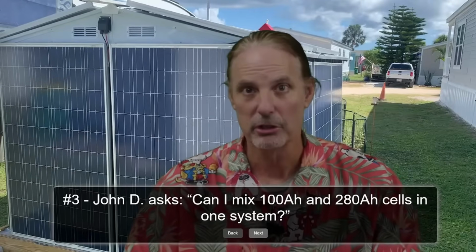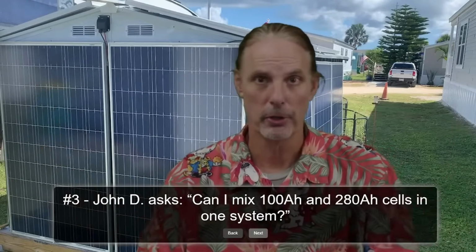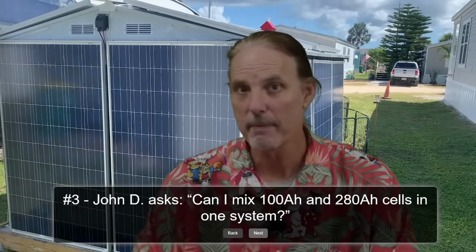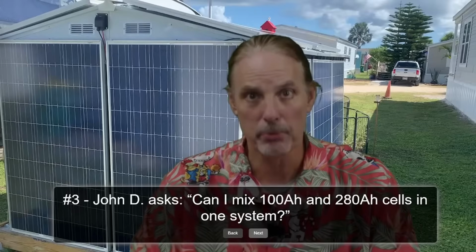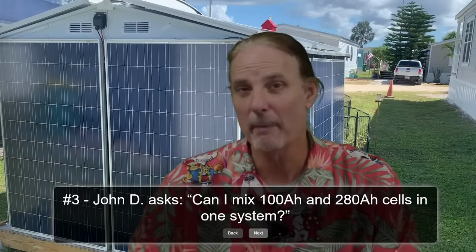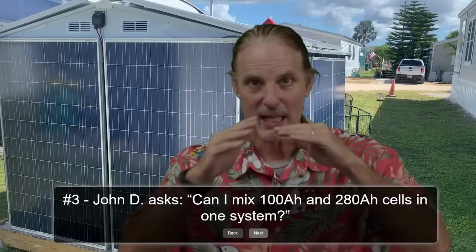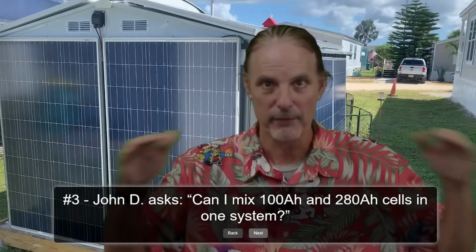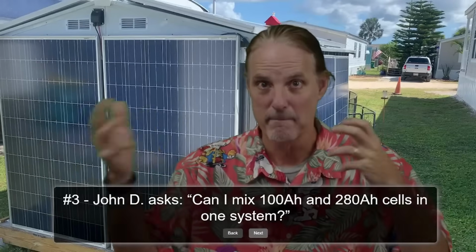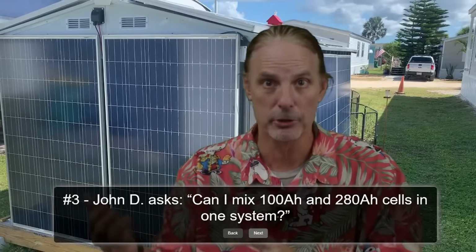There are mixed feelings in the market about whether or not you should do it. My opinion is that every battery should be fused properly to handle its influx and outflux of power. When they are hooked up into a bank, they should be very carefully balanced, and I don't mean perfectly balanced. I mean balanced at the same voltage so that when you turn them on, you prevent large quantities of power transferring from one battery to another.